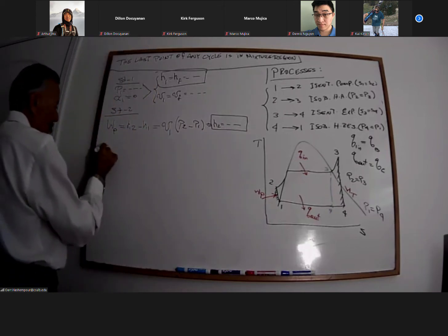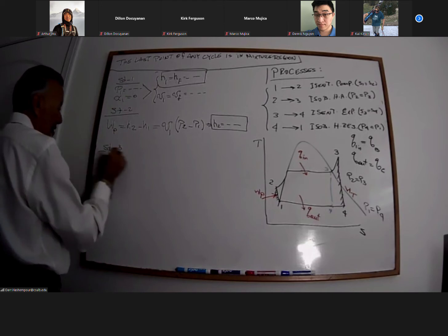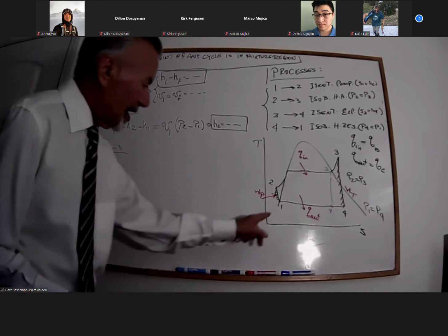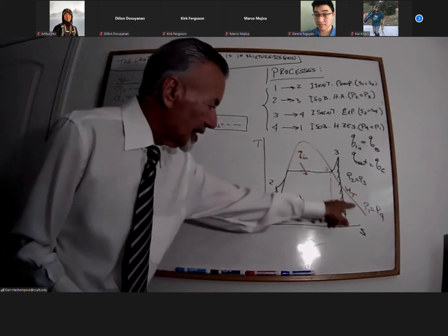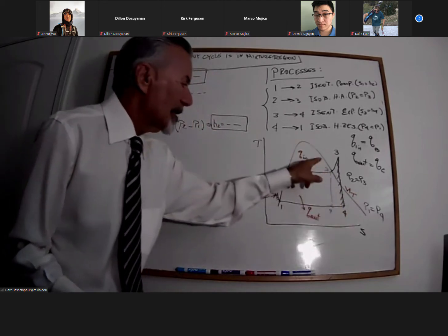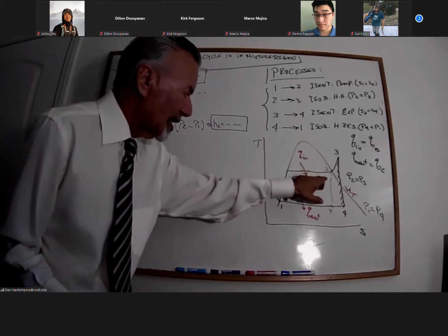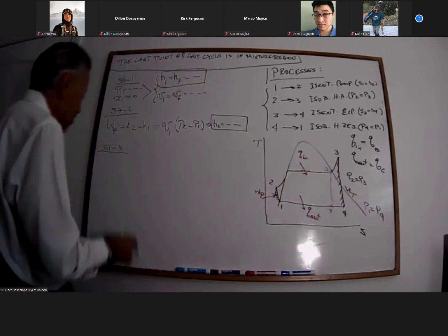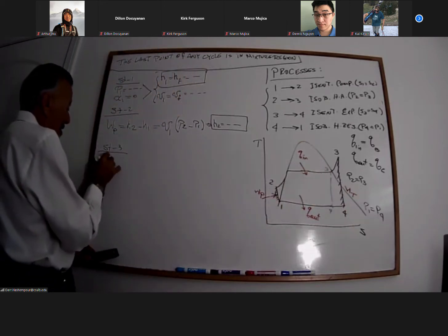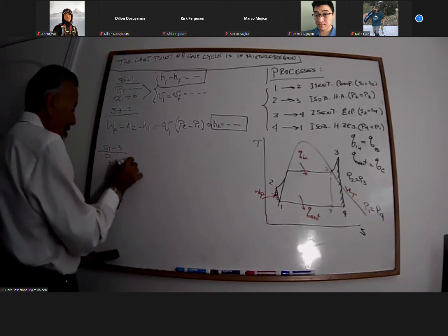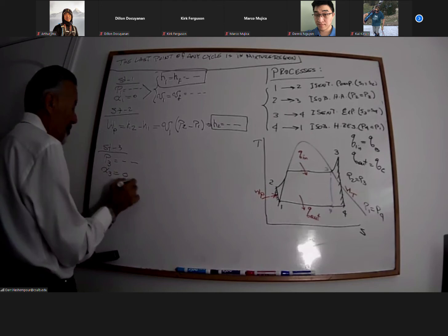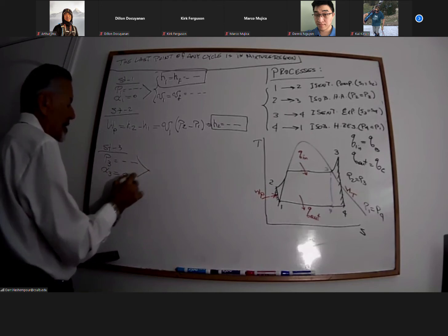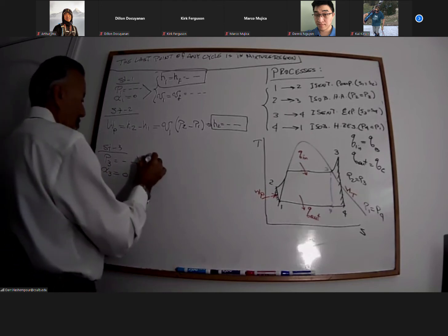Now, we go to state 3. In this case, our point 3 was in the saturated vapor in case of an ideal cycle. So, therefore, I had P3 and my X3 was equal to 1. Once again, I go to the regular table.